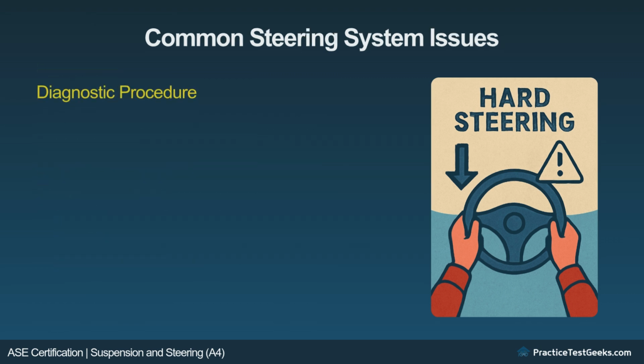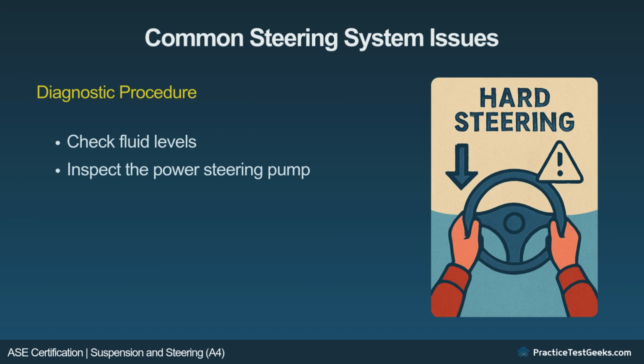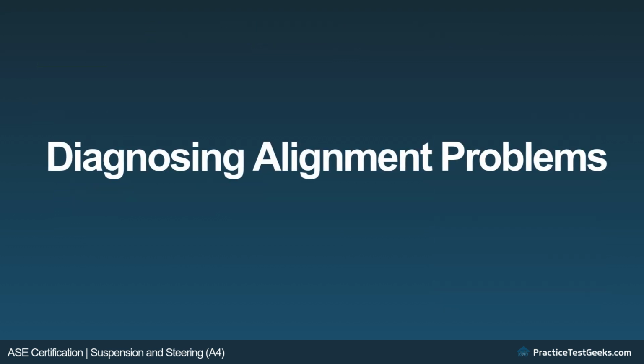Diagnostic procedure. Check fluid levels and ensure the power steering fluid is at the correct level. Inspect the power steering pump for proper operation and signs of failure. Test the steering rack for wear or damage and check for leaks.